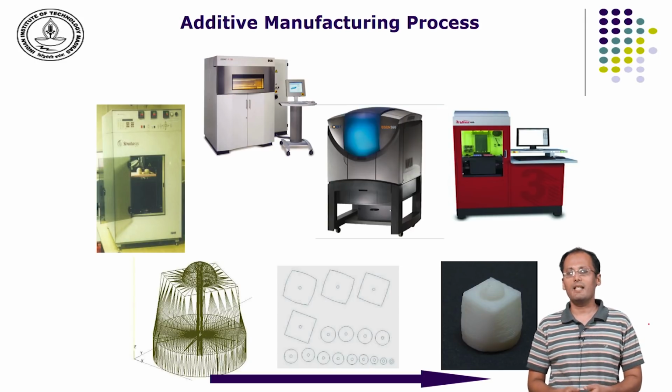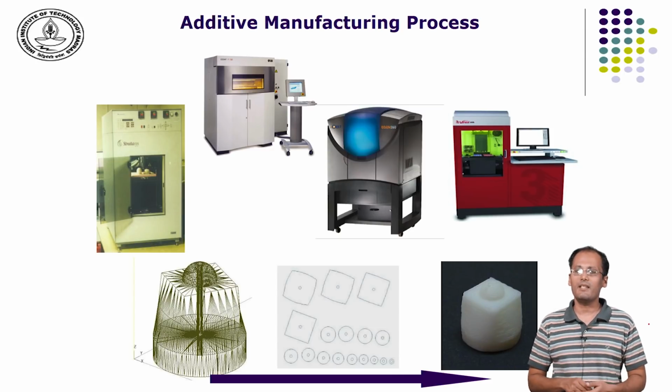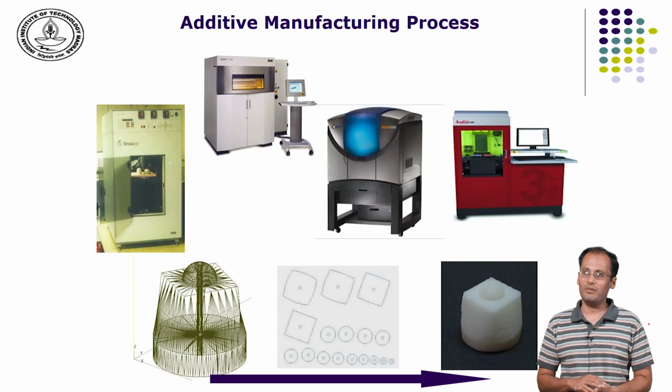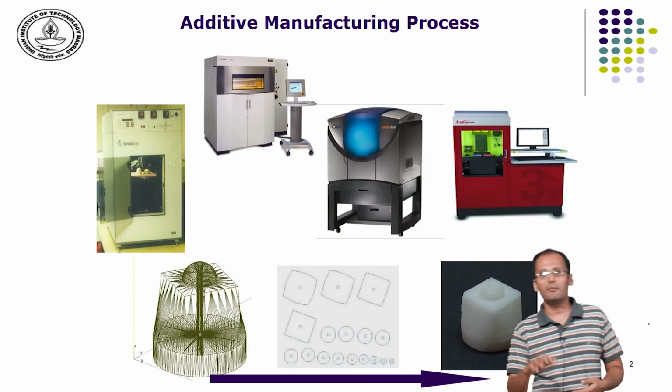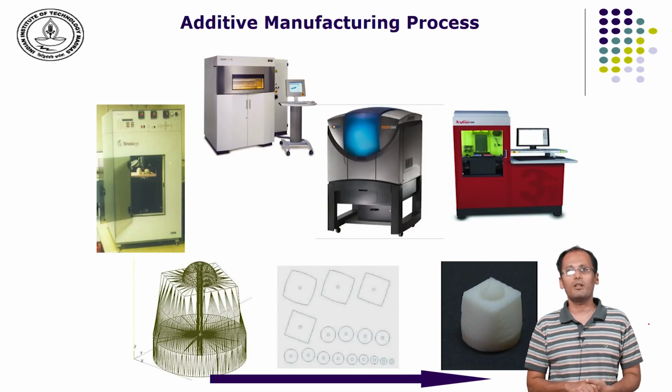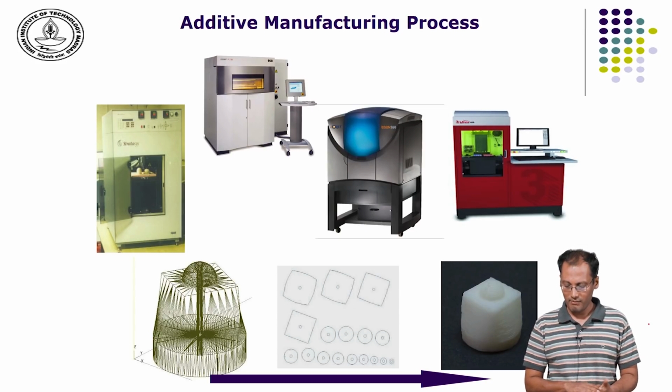And you have the selective laser sintering process, where a laser selectively sinters regions of interest in a bed of powder. And also you have the polyjet process, where, like an inkjet printer, the photopolymeric resin is printed on the bed, and an ultraviolet light source polymerizes the printed resin, and layer by layer again the part is built in a sequential fashion.